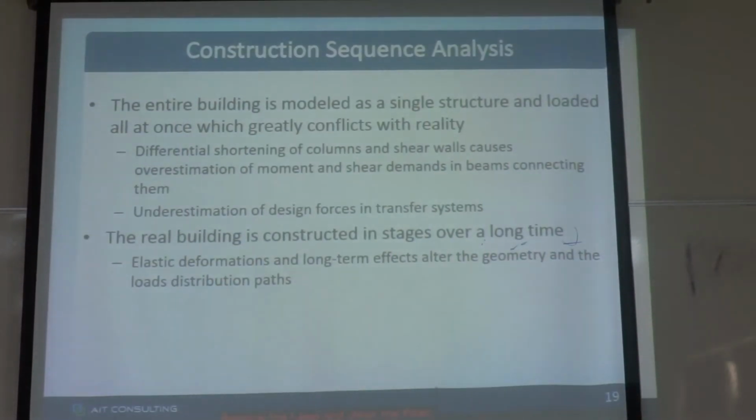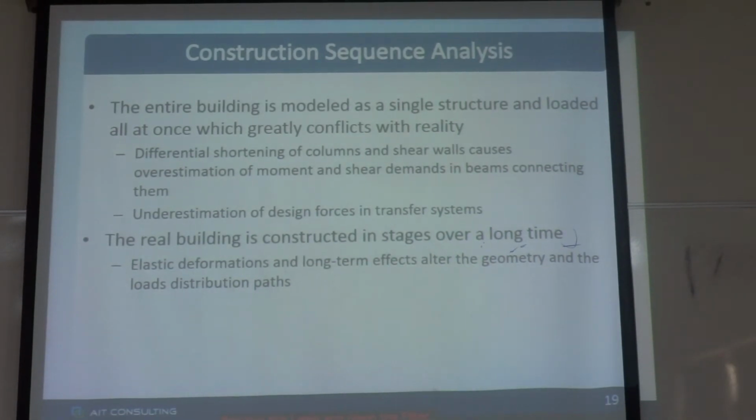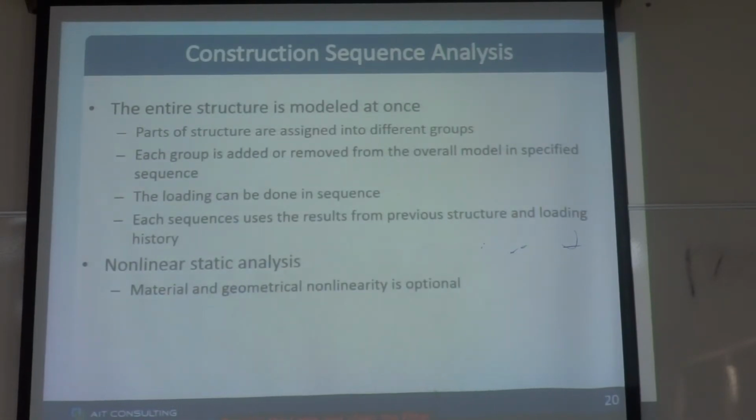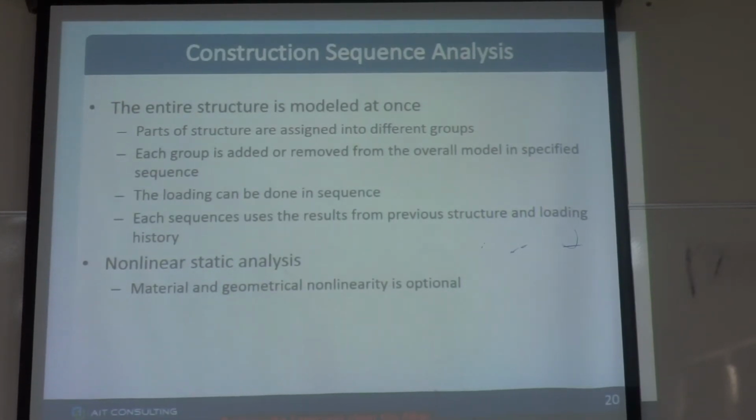This is about construction sequence analysis. Like I already explained, the building is not constructed at one time, so differential shortening can cause moment and shear forces in the horizontal members. This is how to create the construction sequence analysis. This one I will show you in depth.